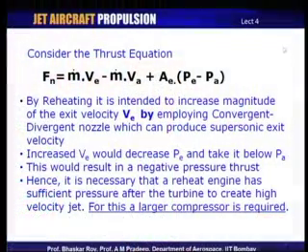So, reheat engines are typically deployed in most of the military engines, and most of the typical passenger or transport aircrafts are unlikely to have afterburning or reheat engines, because as you see they are fundamentally of lower fuel efficiency. In a passenger or transport aircraft, fuel efficiency is of primary importance, and hence that cannot be sacrificed. So, this kind of engine is typically used in military aircraft. Let us just summarize some of these points that we have been talking about.